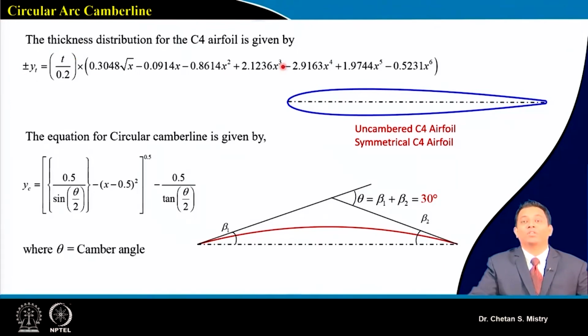Now, as I told, a few aerofoils are available in open literature. So when you are starting with your initial design, or your initial calculation or making of the blade, you need to select those kinds of aerofoils first. Suppose you have the equation available for a C4 kind of aerofoil. Then on this straight line, this symmetrical aerofoil gives the variation of my thickness. It says at 40% of my chord I have maximum thickness.